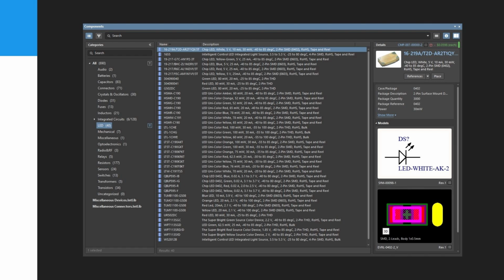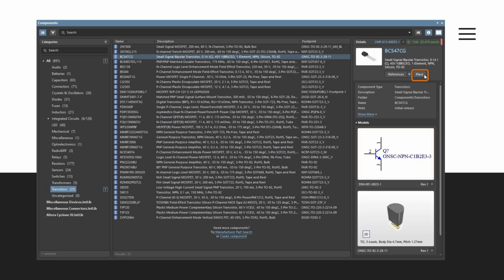The structure of categories reflects component types currently defined on the connected workspace. Use the Data Management Component Types page of the Preferences dialog for viewing and managing component types. To place a component from the panel, you can click the Place button in the Component Details pane. Then, the cursor will automatically move to be within the bounds of the schematic sheet and the component appears floating on the cursor. Now, position it and click to place.